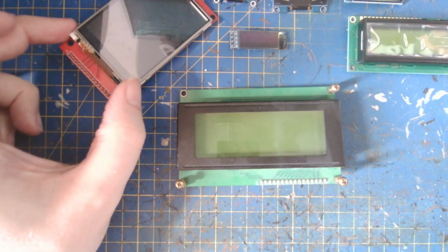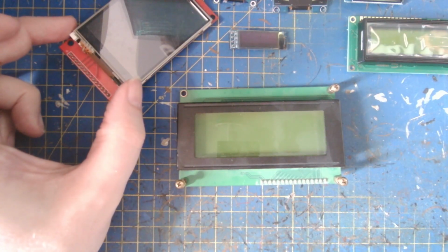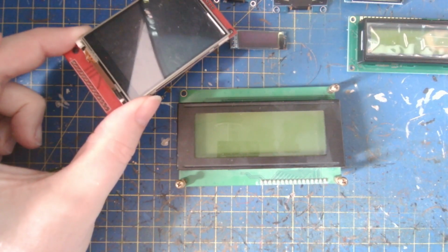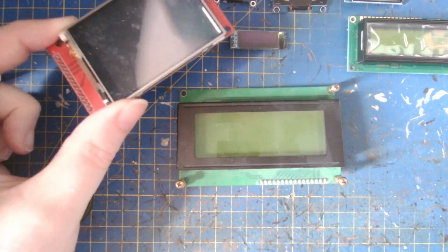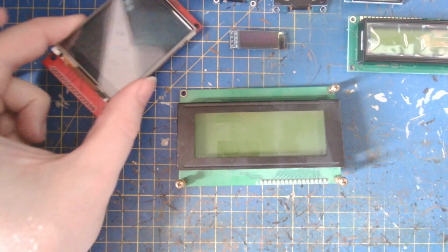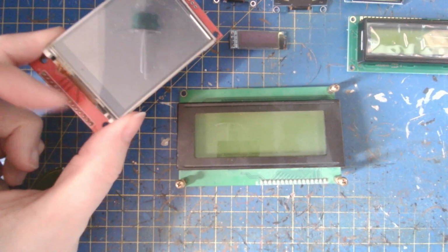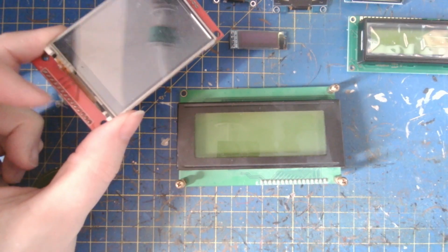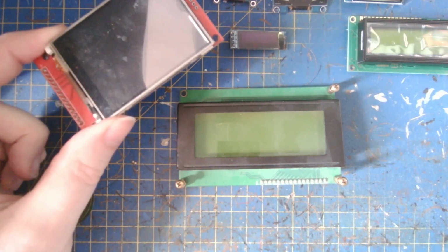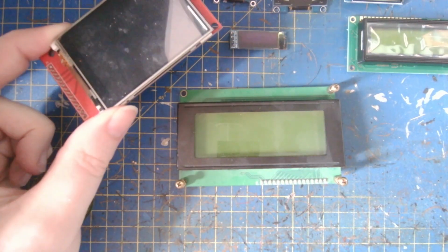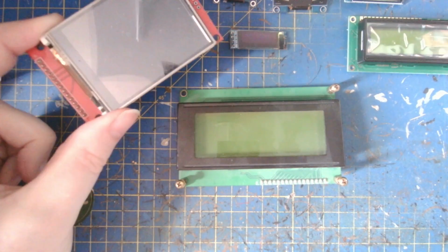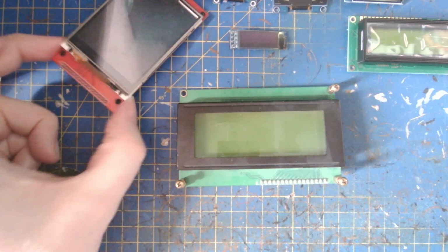In addition to that, there is a clock line, which is controlled by the master, and it dictates the speed. These can be fast: 10 megahertz, 20 megahertz, 40 megahertz, 80 megahertz. It's a good choice for a colour screen. You've got a lot of data to shift, and away it goes. There's also a select line, and in the case of these, there are some other lines. Very commonly, you'll have a data/command line, which tells the device whether what it's about to see is data, as in what it needs to show, or a command, in which case it needs to respond in a different way. It uses a fair few wires. It is fast.